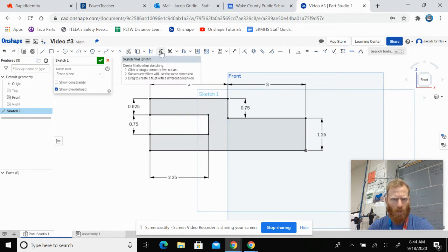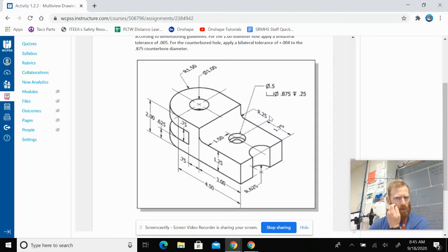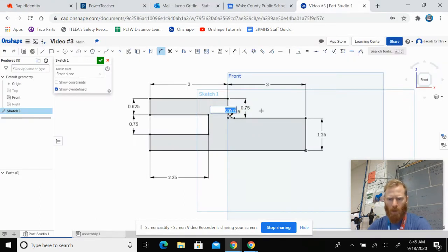And how you use that, you hover over it and it'll give you a little bit of an overview, and you can click it and then select the two faces that you want the round over to join in between. So see, it goes ahead and throws it in there. It even shows you a little mouse left click, gives you a chance to change it. But ours is already a radius of 0.25, so we're happy with the default, and then just enter. All right, so now I can pull this little radius out just to show you that's already in there.